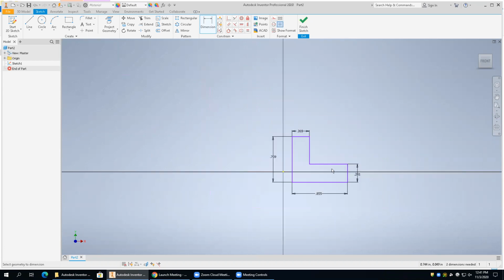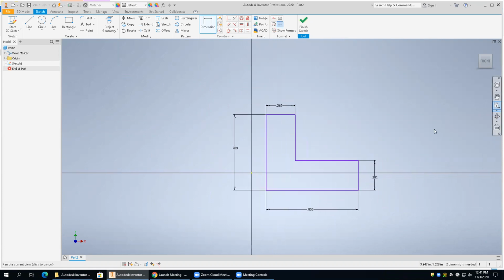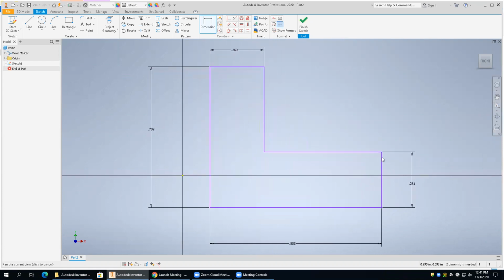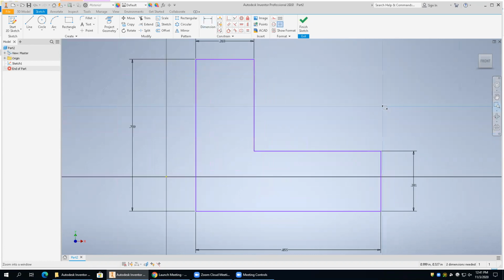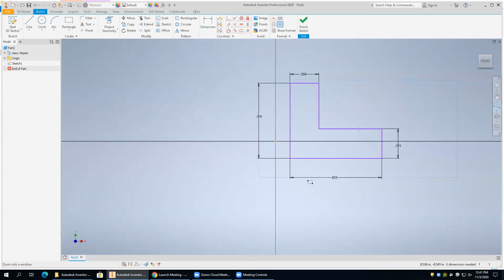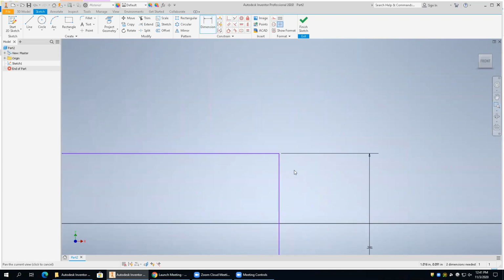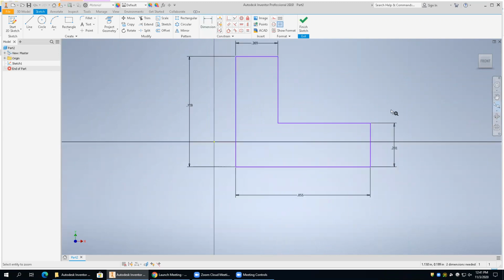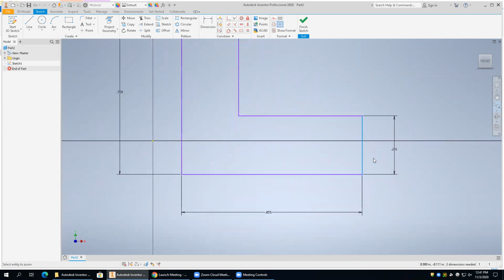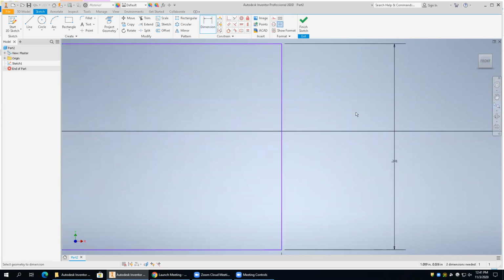So if you zoom in or out with the wheel, you can come over here and say zoom all. Zoom it full view, okay? Zoom window, just a window like an AutoCAD window. You pick a point, pick another point, okay? Or you can just hold it, drag, release, okay? There's that tool. Then you also have zoom object or zoom selected. So what you can do is come over here and select that object. It puts it right to it, okay?